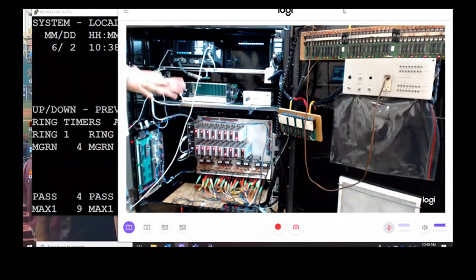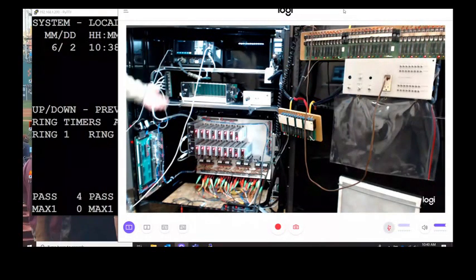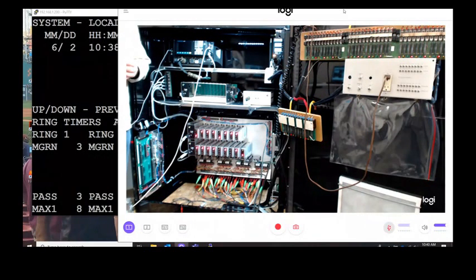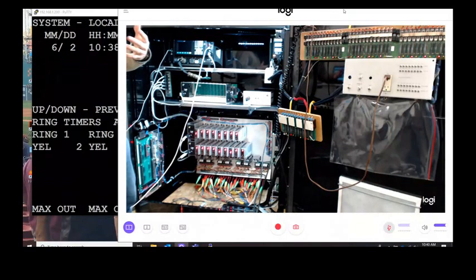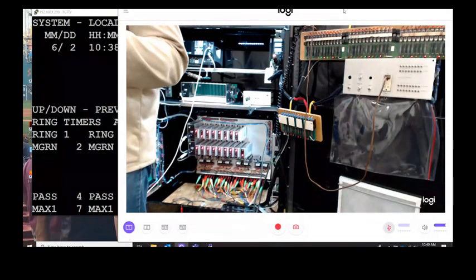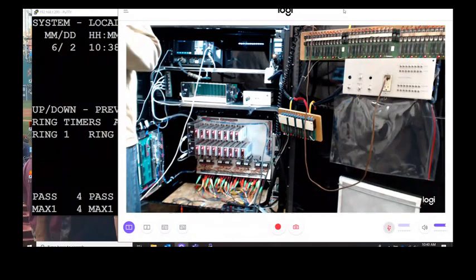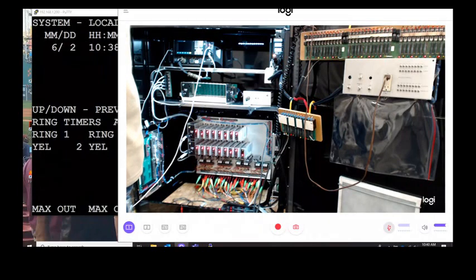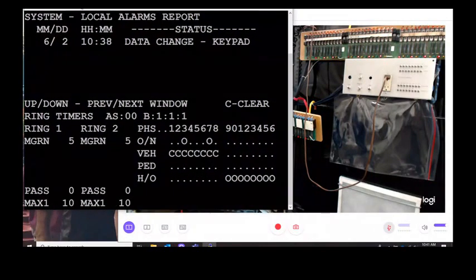That didn't really flow as great as I wanted. I didn't have any bad BIUs. If I had a bad BIU to plug in there, that would have made more sense, because I could have replicated the failure better. But I wanted to expose you to that process, because that's something we will continue to have you do over the phone when we're troubleshooting TS2 cabinets with BIUs. It's so you understand the process of doing it one step at a time, one BIU, then the other BIU, and we go from there. Typically, we've had a lot of success in doing that process.